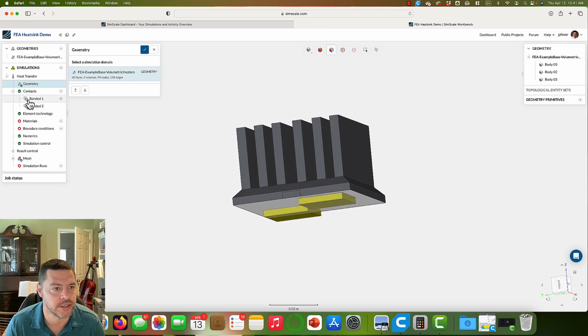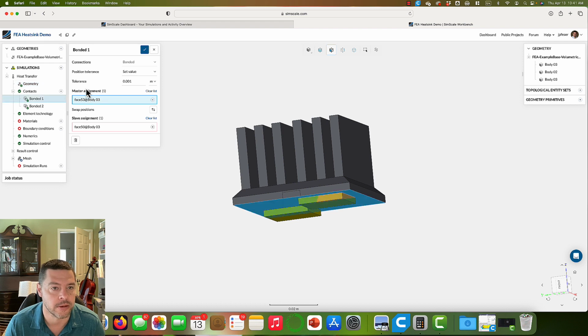Sometimes it's a good idea to check out how it actually created that. So for example, what it's saying is that if those 2 solids touch each other to within 1 millimeter, which is actually probably not a good value here, then it's going to consider that part of the bond. I would say we should probably refine that a little bit because the size of these solids is only a couple millimeters thick.